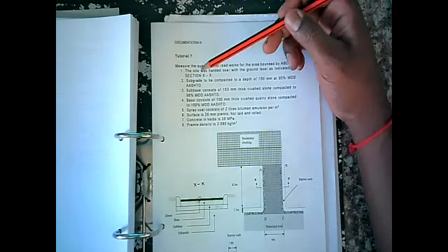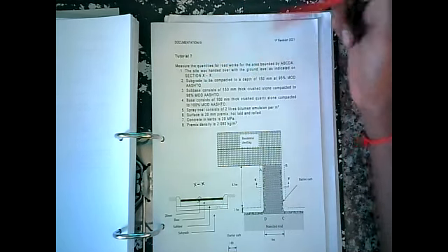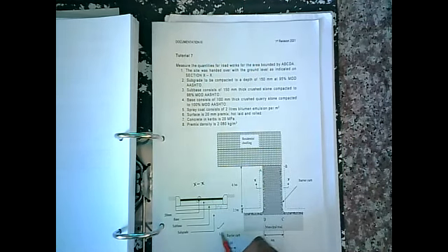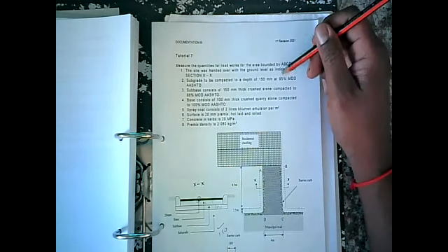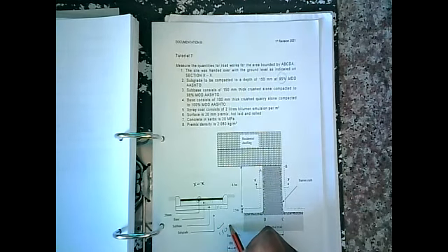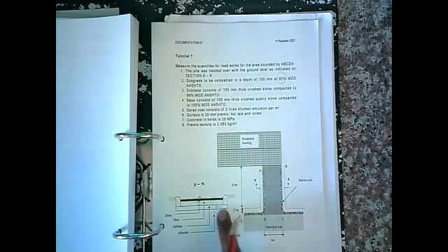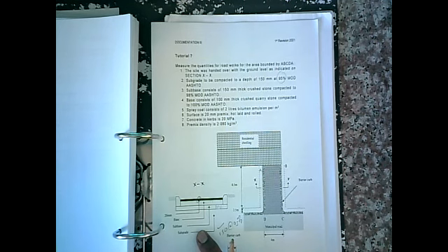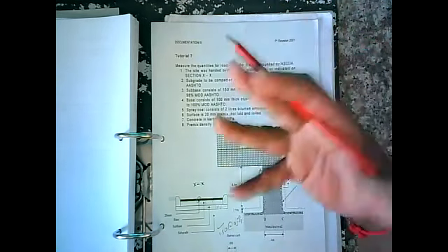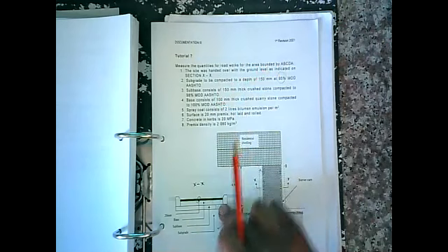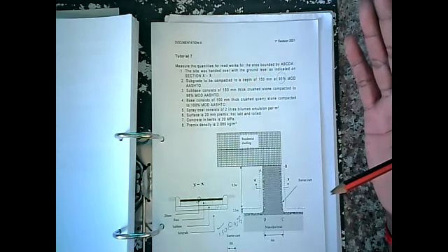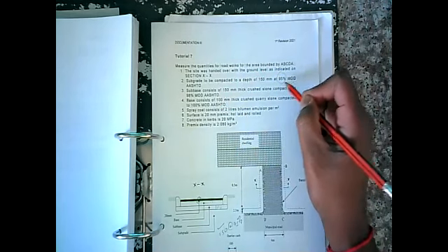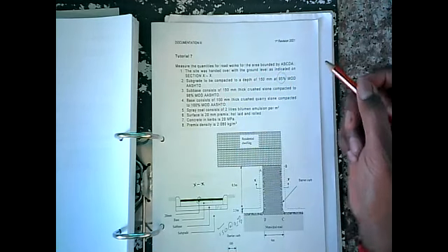Right, so subgrade to be compacted to a depth of 150 millimeters at 95% Mod AASHTO. Now we're given a condition, so we have to apply that condition to that particular area of that pavement. Therefore, it has to be quantified. You may think it's already there, so why would you have to apply extra work to it? Because we need to rip, compact, and get that percentage of compaction.